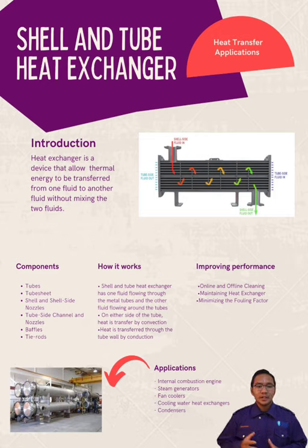Heat exchangers are used in a variety of applications in power engineering, including steam generators, fan coolers, and cooling water heat exchangers and condensers. Other than that, refrigerators and air conditioners, for example, employ heat exchangers in the opposite manner to a central heating system, in which they extract heat from a compartment or room that is not needed and pump it away in a fluid to another location where it may be discharged out of the way.